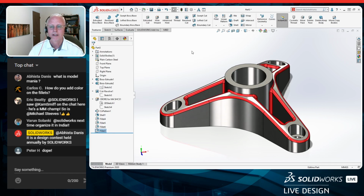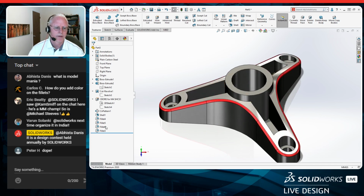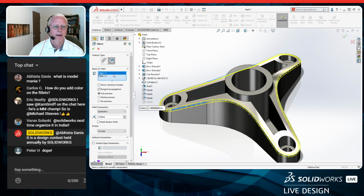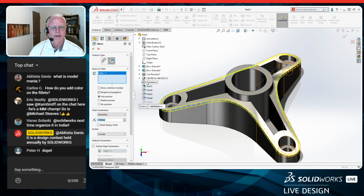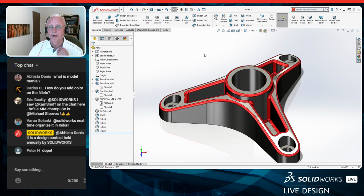So you've got to watch out for that one. So let's just undo. Back to that edit feature here. Okay, we've got to put our fillet back in. I'm just going to clear everything and choose this edge, and we'll choose our shell feature. Everything goes again. So that was one way with the Fillet Expert.